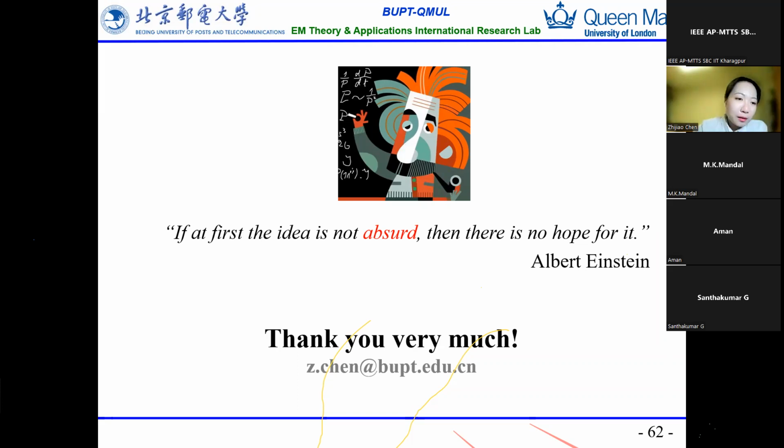So let me repeat. Brennan says, hi, by using waveguide with laminates as a dielectric in the distribution network, the problem of loss in the feed network or power dividing network will not be solved. Theoretically, the loss will be the same as the microstrip transmission line because the majority of the loss belongs to dielectric loss, which is the same in both.